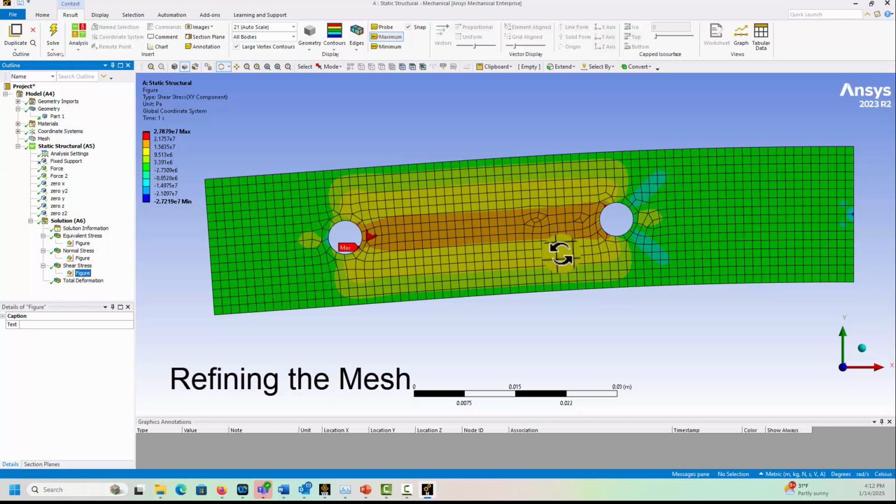So I would leave it easy so you could do fast iterations, and you could even back up and go to a little bit coarser mesh. You could also try doing your meshing a little bit differently than this, using tetrahedral by putting a refinement or size elements around the holes, in addition to the global sizing. But I'll leave that up to you. This is an easy solution that works pretty well.